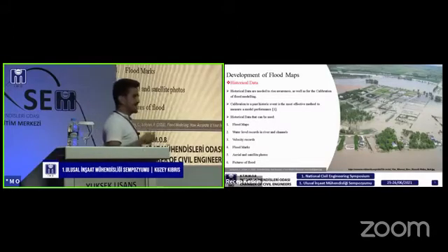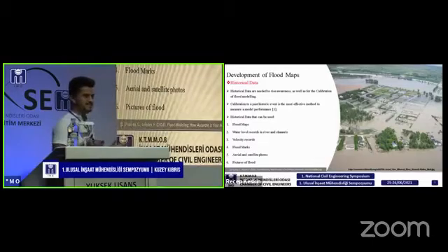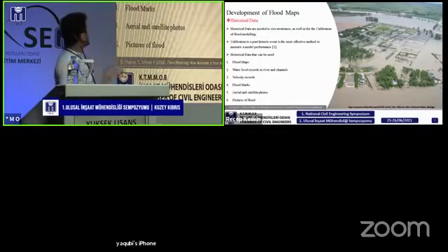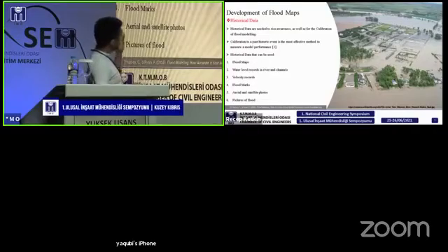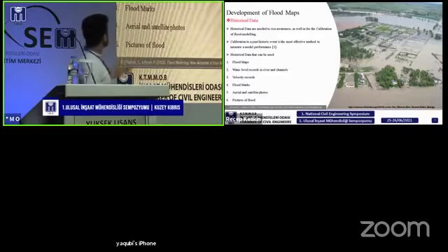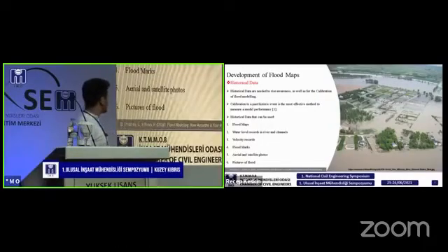Historical data that can be used in the flood modeling is flood maps, flood extent maps, like which area was covered under the floods, with water level records. For this case specifically of Dikmen, we have only the flood extent maps. The others are kind of missing. Water level records in river and channel, velocity records, flood marks.